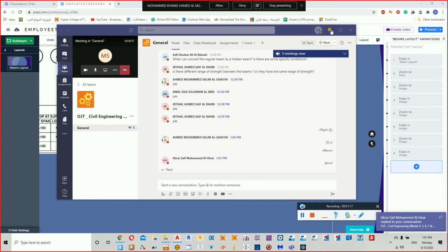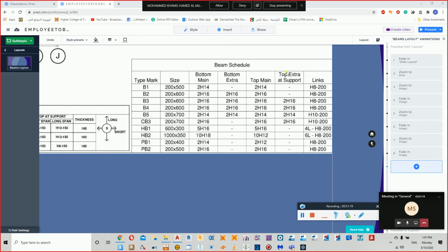Okay, so once again, for understanding this one, you need to understand the behavior of the bending moment. When it comes to the span, we are talking about a parabolic. For a parabolic, lesser bending moment values here, more bending moment value here. If I supply one reinforcement from the beginning till the end, it's okay for the sides and the center, which is the peak. Then it's fine. No need to supply extra reinforcement.